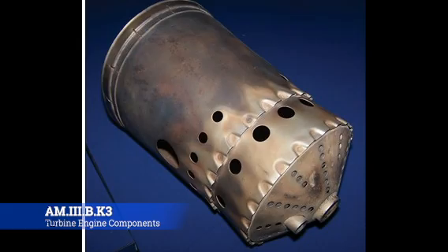So you increase the surface area of the droplet, and you increase the amount of oxygen that fuel is exposed to, and therefore you increase the rate at which it can burn. So it's a lot more efficient the finer you can get the droplets. So it's always a ratio between surface area and droplet size or mass.